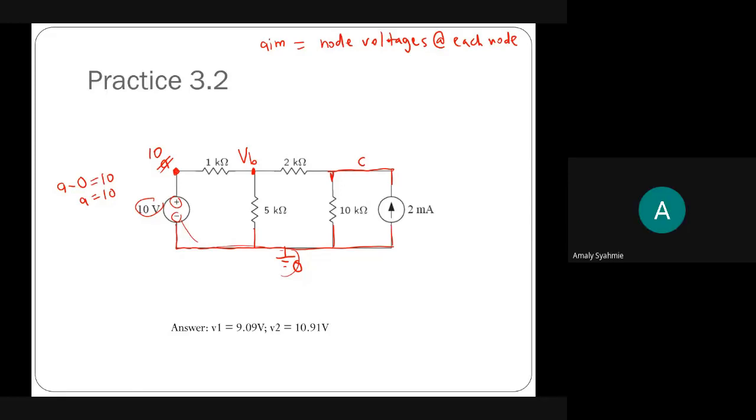We know the I. This is a current, right? A current source. What should you know? You need to know the voltage of this node, right? So, do you know the voltage of this node? No way. So you can name it. In my case, I just put VC.